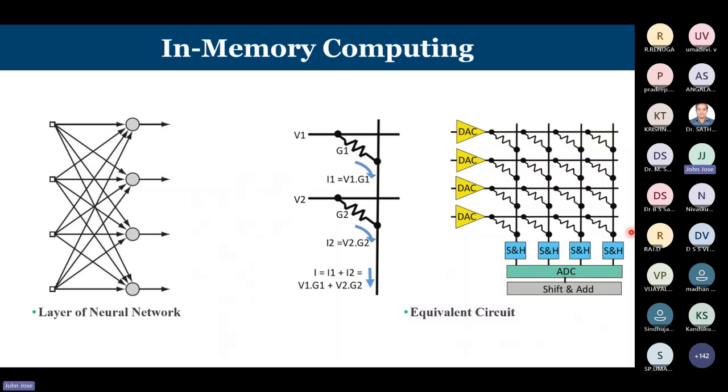The problem with the memristor design is that I cannot change the weight. So I have to do the training and fix the weight. So this will be an already trained system. I have to find out the weights, and once the weights are finalized and converged, put in appropriate memristor values, and hereafter it acts as a neural network. So only the inputs change now, and you get the corresponding output. So it's a weight stationary concept.